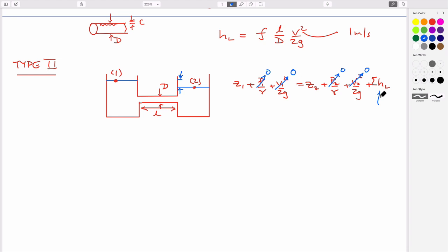There will be a velocity in this pipe, which will be friction factor, length over diameter, velocity squared in the pipe over 2g. And the only terms we have are relative to our datum; you can choose your datum wherever you want. If you choose it here at z equals 0, then this ends up just being z1, and this goes to 0. So in other words, the head loss in the system has to equal z1 minus z2 in this particular case, right?